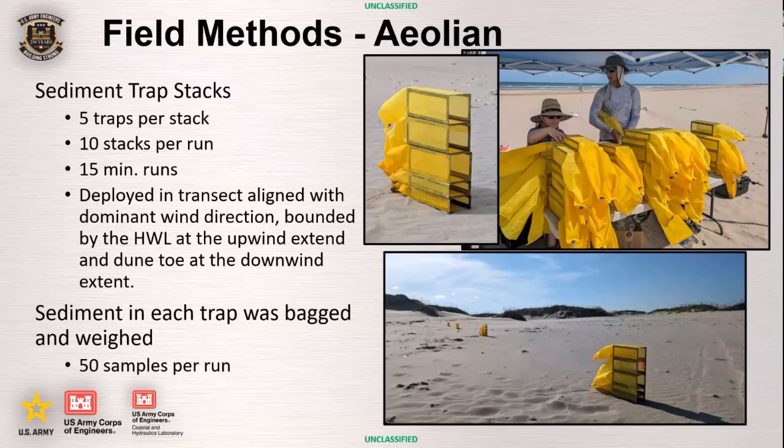So on the sediment side of the equation, we care about sediment being pushed into our channel, right? And we have to factor in that beach fetch, or that lateral distance that the boundary layer is getting used to the underlying surface roughness, is very much a driving factor. And what that means within the aeolian realm, right, is that where you're at on the beach matters in terms of how much sand may or may not be moving. So the best way to make sure that we're capturing the maximum sediment transport rate along a transect is to deploy a series of sediment trap stacks.